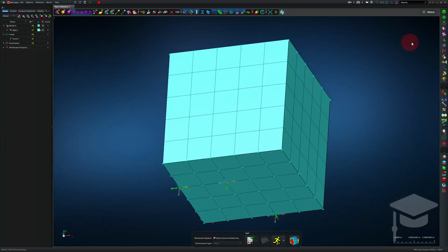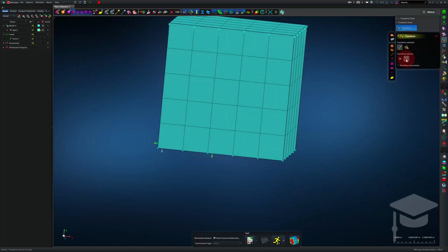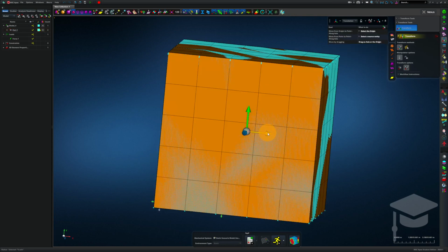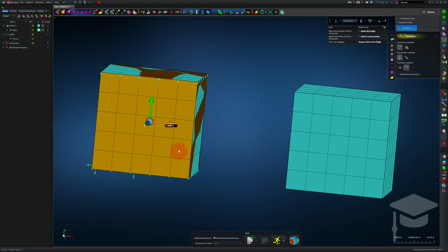We're back in Apex. I'm going to pull up the transform tool and use that to make copies of this cube. So I've selected the copy option here, and I can click on the cube, click on this axis here, and I can enter how far I want the copy to be placed. The cube is 1 cubic meter, so if we type in 2 meters, that will give us a new cube that is a generous distance away from this one. See? So that looks like a pretty nice spacing. I can come in here and type 4, 6, 8, and 10.